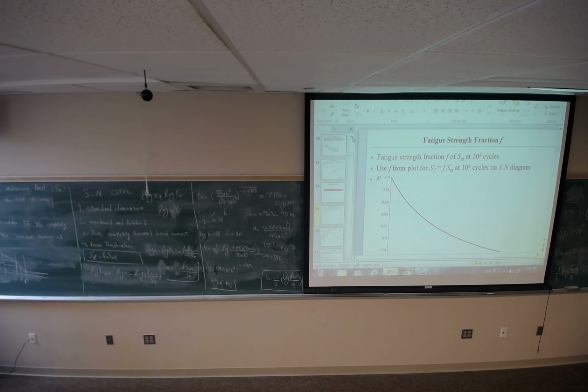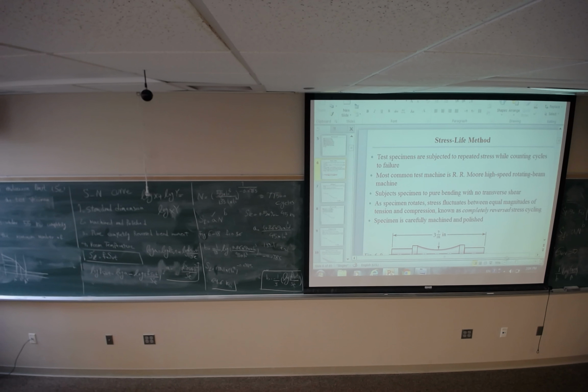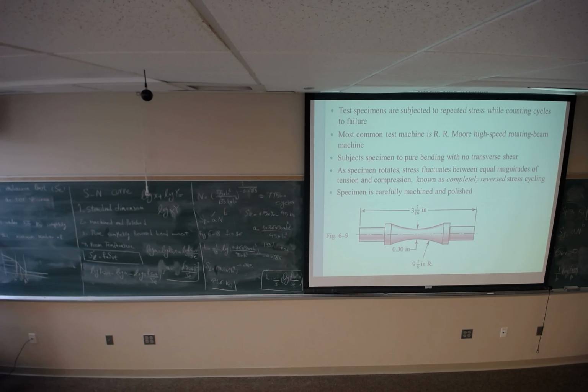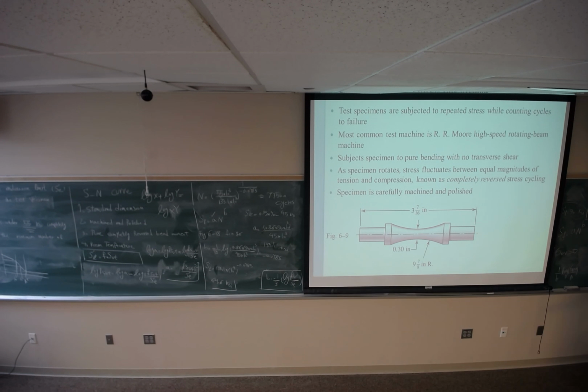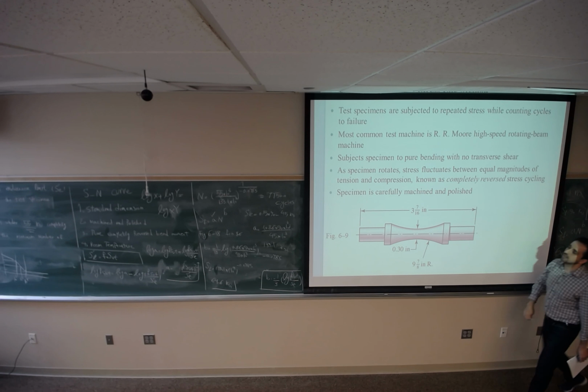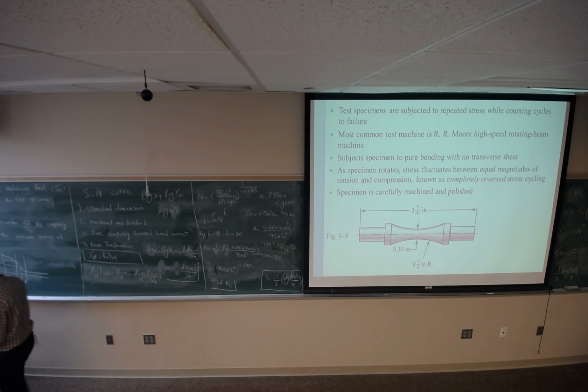So this test specimen under this loading is going to run for almost about 78,000 cycles. If I tell you the speed is 1 revolution per second, you can figure out how many seconds or how many hours it's going to work. 77,500 seconds. Then change it to hours. It's going to tell you for how many hours this component or this system is going to run. So you can expect the life of this test specimen. Makes sense?